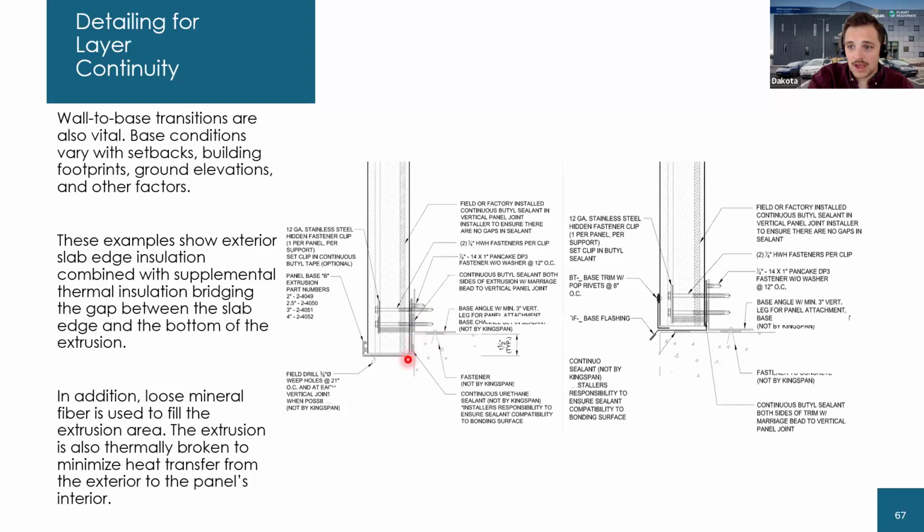We have conditions where we have extrusions that can accept that first channel of IMPs. This is very typical, keeps everything dry, keeps everything from seeping up underneath into the building itself. Additionally, if we want more of a flush condition where the IMP is lining itself up with the slab as well, we have some nice space. We have some silicone in there to make sure that we're nice and airtight. Then, of course, flashing and lip. Pretty standard stuff. But again, if you're confused about that, we can get into it at a later date. No big deal.